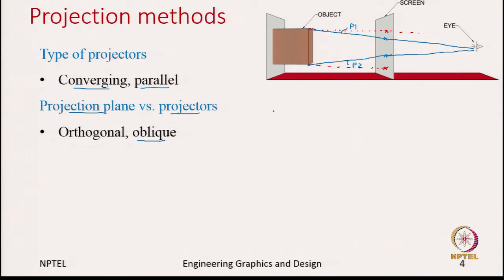But in these red lines, let us say we look at the same thing in the top view, looking from the top. Now, what we see as the cube is a square, and this is your projection plane, which we will see as a line, and let us say we have an eye here, but very far, meaning that the observer is at infinity and the projectors are parallel.